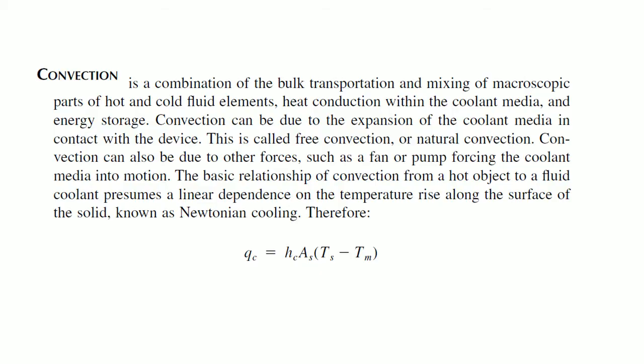Now, come back to my slide. Convection can be due to the expansion of the coolant media in contact with the device. This is called free convection or natural convection. So, what happens here is buoyancy is set up. The moment something expands, the density comes down and immediately it will try to rise up. This is the basis of natural convection, which is good. My body gets naturally convected like yours.